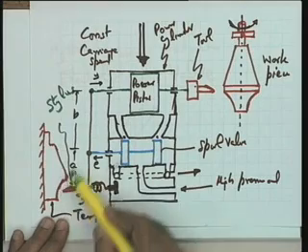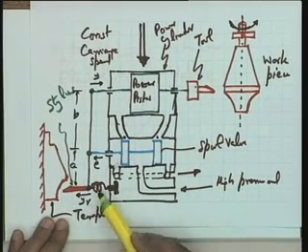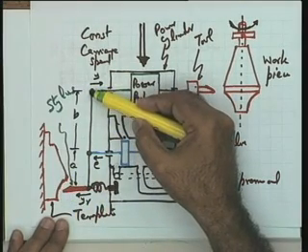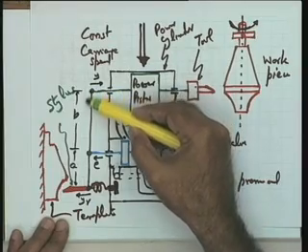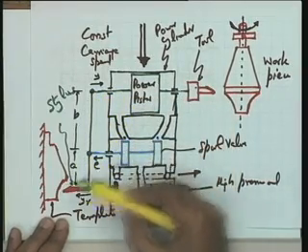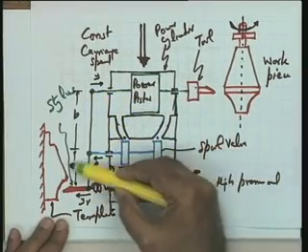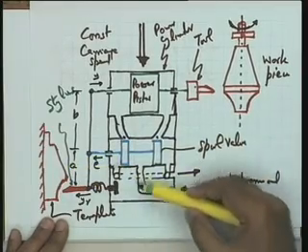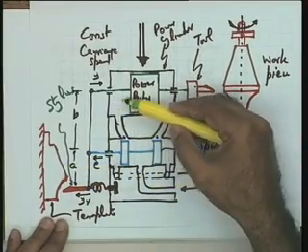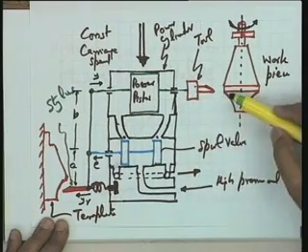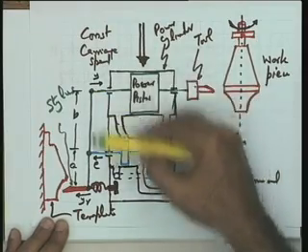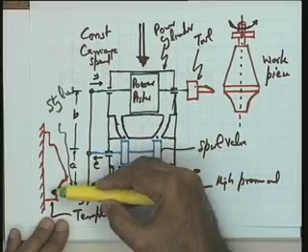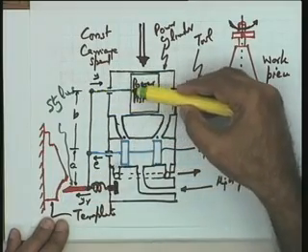As soon as the stylus movement on this template gives you YR, this particular point is going to act as a pivot, and hence the lever will move this way, pulling this particular spool this way. As soon as this spool is pulled this way, the high pressure oil rushes to this side, which moves the power piston this way, and hence there are two forces on this particular lever. One force is in this direction and the other force is in this direction.